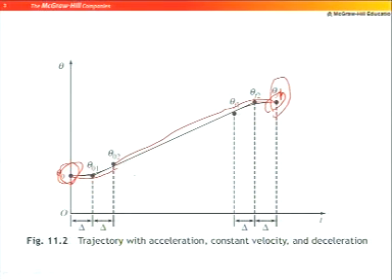I repeat, I want to go from theta 0 to theta f, I will go along a certain fourth order polynomial, a straight line, and then a fourth order polynomial. Now, what are the coefficients of these fourth order polynomials? What is the equation of this line? I am going to derive that now.